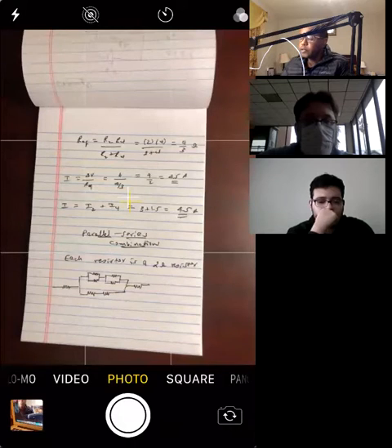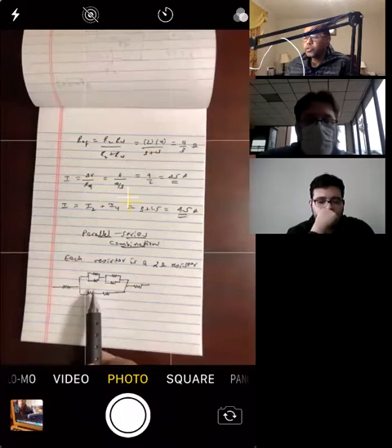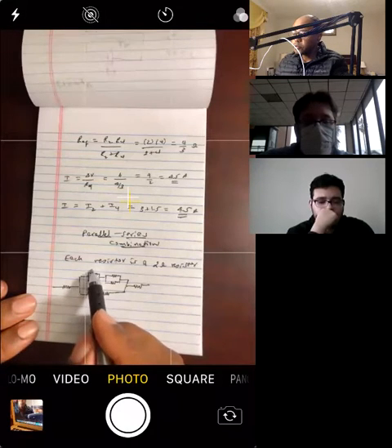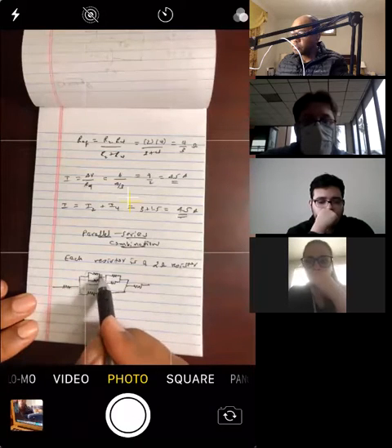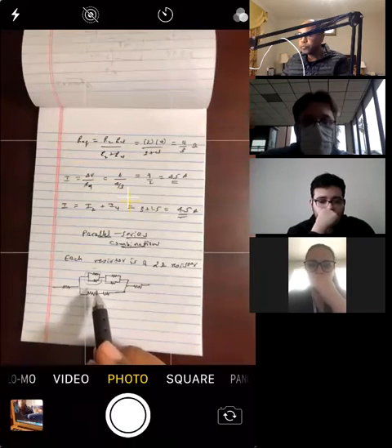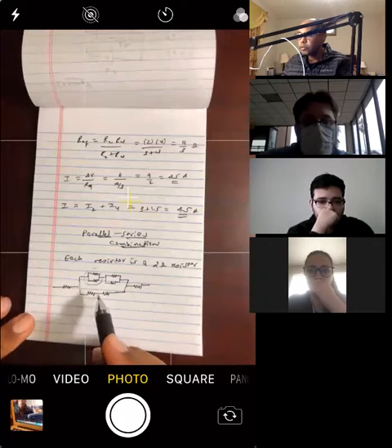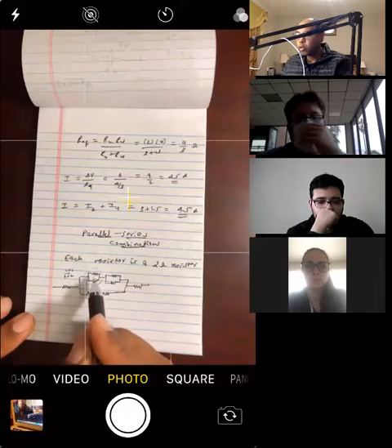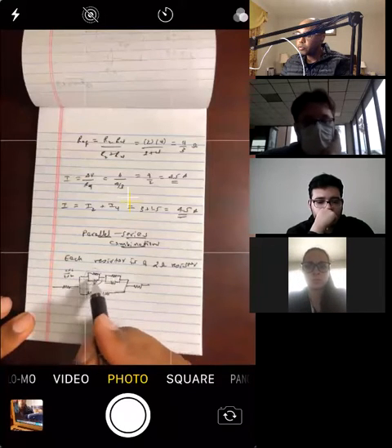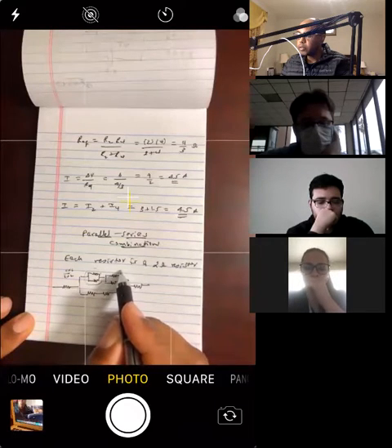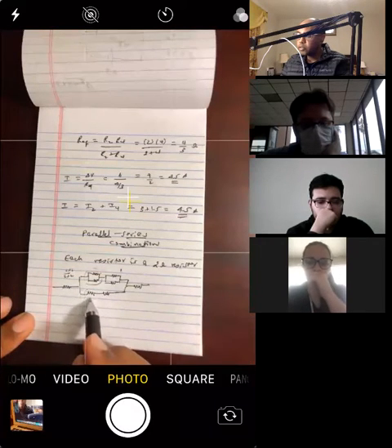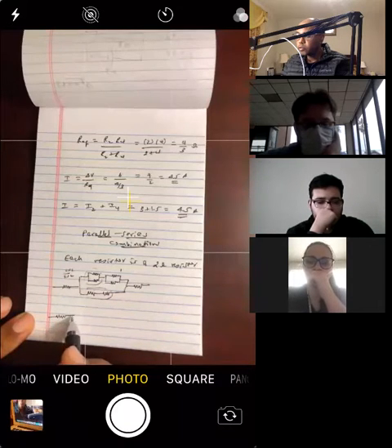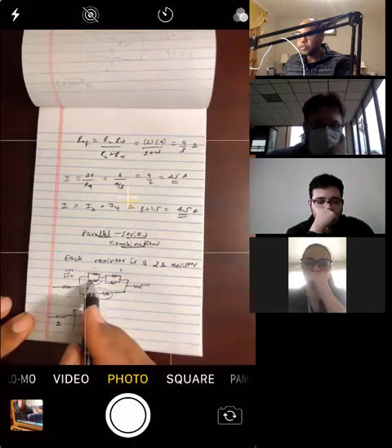Okay, so what you can do is simplify it by combining those resistors that are in series or in parallel. All right. So first we can combine these two. They're in parallel, right? So what's the equivalent resistance for these two? It's product over sum, right? So this will be 2 times 2 over 2 plus 2, which is 4 over 4. This can be replaced by 1 ohm. The same thing over here: 2 times 2 over 2 plus 2, this also can be replaced by 1 ohm. How about this? This is sum, because they're in series, right? So I can simplify this one into the following. So there's still 2. Now we can replace by 1.